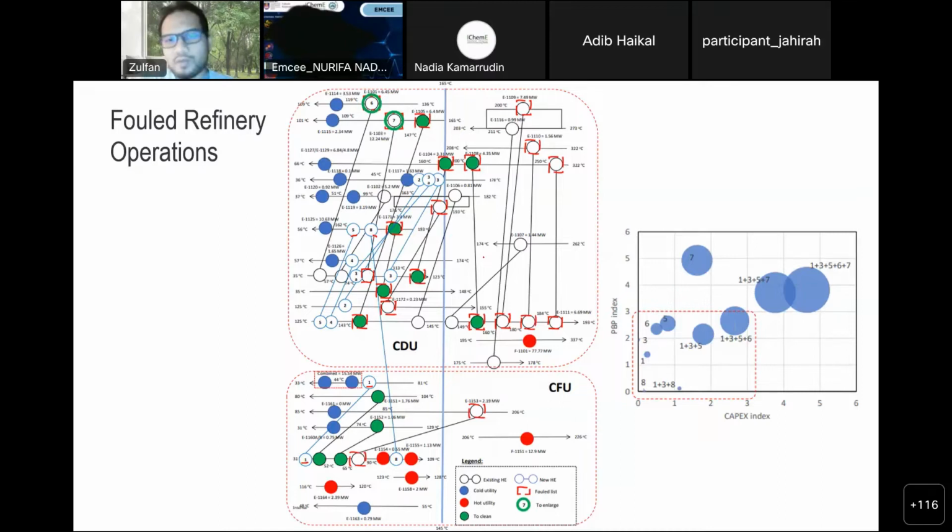So in the end, when we weigh them, we put this into the process simulation to see how the system behaves, because the refinery in this case is what we call a crude distillation unit, and then this is obviously the crude preheating train. So they are connected sequentially. So if we do some recoveries at the front, it will disturb the whole entire train.